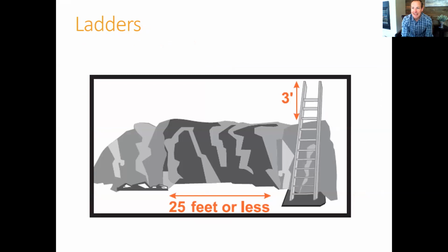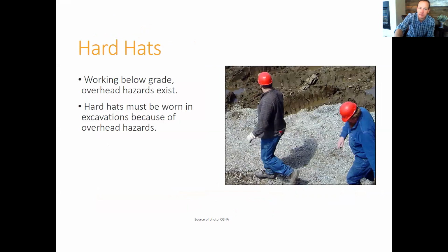It needs to also extend 3 feet above the top of the trench. This is a standard for a ladder wherever you're using a ladder, because somebody needs to be able to grasp that ladder and exit and step over the edge of the trench. So it needs to go up 3 feet. There are overhead hazards usually around trenches and excavations. So you need to be concerned with that, because OSHA requires that anytime there's an overhead hazard, you have head protection. So wearing hard hats.